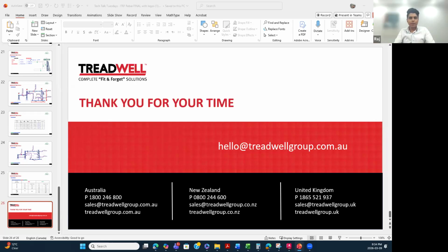It's very similar to every other FRP application, where to get a good sense, one doesn't really need to just take the material cost, but rather have an overarching view of the project cost, including the installation cost and the design life advantages that FRP offers. So broadly, let's say a structure which has a 50-year design life with a conventional material versus with FRP as embedded reinforcement, which can exceed up to 80 years. So there are benefits in the long term, if that answers your question.